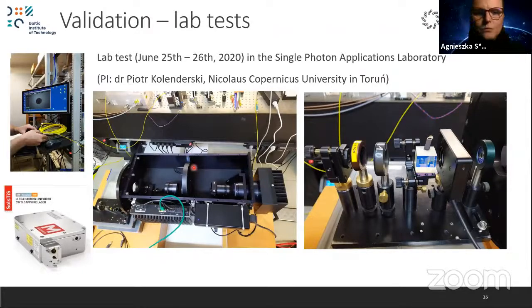And this is the polarimeter, and this is the optical test system. So here you have the optical fiber, and then the next is the neutral density filter. Then we have the lens, the beam splitters. The beam splitter, because the light going out from the laser is 100% elliptically polarized, but we want to test the linear polarization, so we need to have the beam splitter, and the light passing the beam splitter will be 100% linearly polarized, perpendicular to the optical bench.